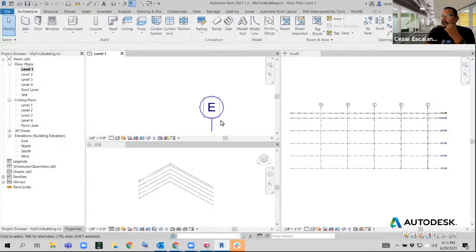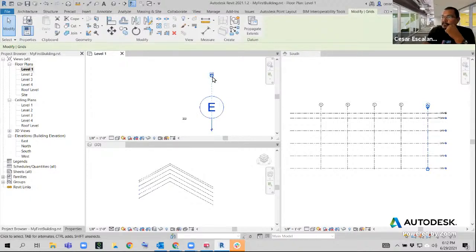Notice how the work plane, which is the hollow circle, is still telling you that the work plane is this location, but for this particular view, the projection of the grid is a little shorter, and that's why it's called 2D, because it's 2D specific. That's what it means.